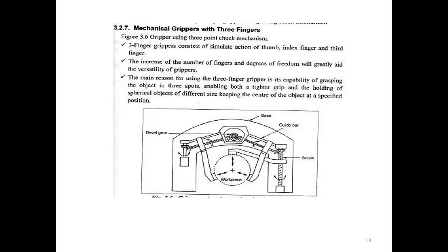Okay, so particularly the three-finger adaptive gripper, which is for advanced manufacturing and robotic research. It adapts to the object shapes for a solid grip, which enables the users to focus on the task and not the grasping. The adaptive gripper has three articulated fingers, which have three joints on it. Gripper weight is 2.3. Grip force is 30 to 70. Gripper opening will have 0 to 155, whereas the case diameter for encompassing is 20 to 155.